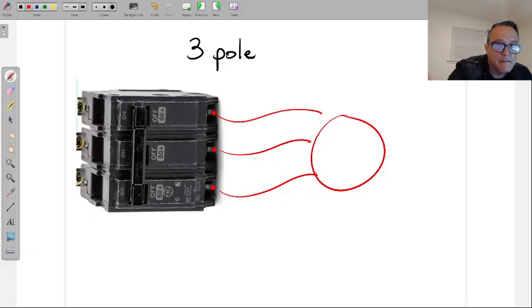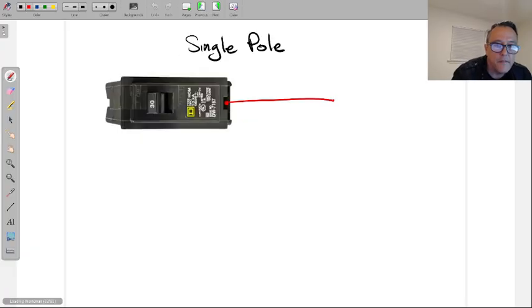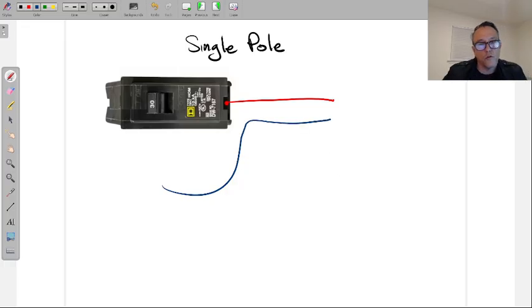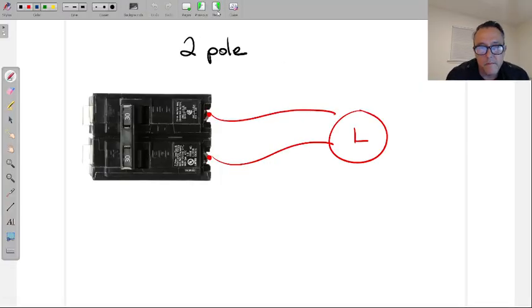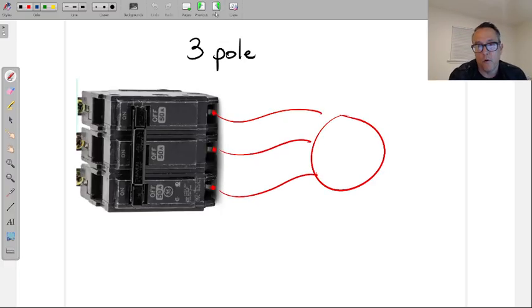So going back to the beginning, this is a single branch circuit. There's only 1 wire leaving here. The neutral will follow along with it because the neutral for these single circuits will need to be part of energizing this equipment. The ground, don't worry about it. Yes, it goes everywhere, but it's just for protecting the system, not for running it. A multi-wire branch circuit would be this one. 2 wires, more than 1. And also to include the 3-pole breaker as well.